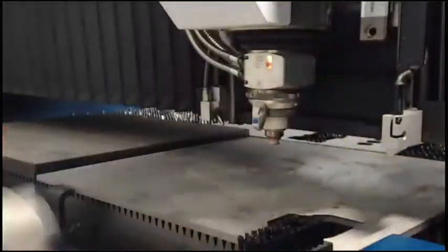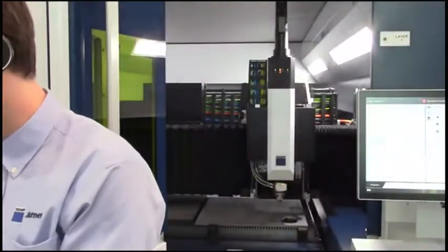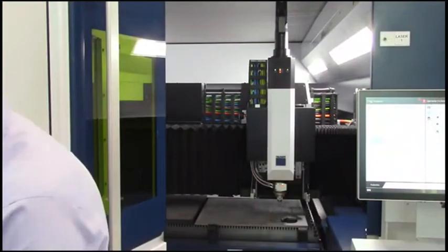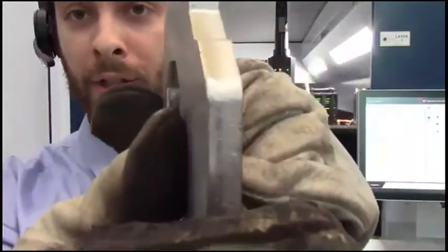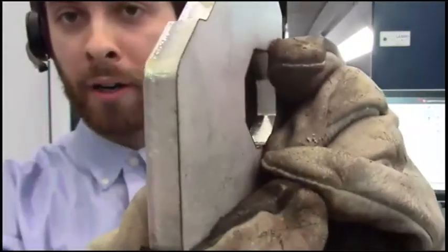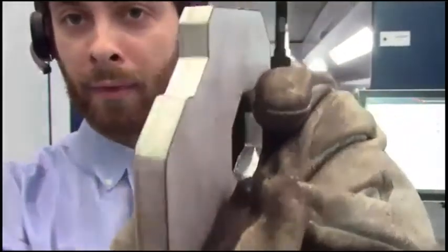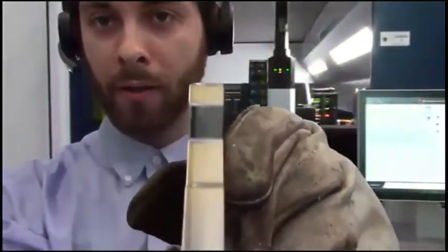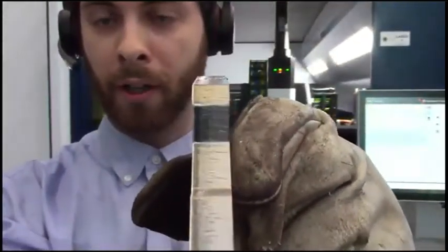And I'll lift it up. There we are. And actually, even though I had my potentiometer set at 70%, it still cut. It's actually only in that centerpiece that it was doing that. On the outside, it was full speed, 267 inches per minute. You can see a really nice edge there. No burr. That's the underside right here. Really nice, straight, really perpendicular cut.